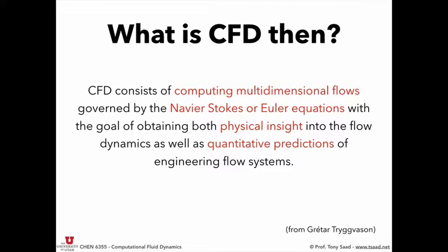We're going to focus on computing multidimensional flows. We may be stuck with 2D for all practical purposes in this class because 3D is going to be expensive for us. But computing multidimensional flows governed by the Navier-Stokes or Euler equations. Okay, and those two equations you've probably heard of. We'll discuss what they are. The Navier-Stokes equations govern the flow of incompressible fluids, incompressible flow. The Euler equations, they're the inviscid version of the gas dynamics equation. So if you're looking for compressibility, shock waves, we look at the Euler equations, or their viscous version, with the goal of obtaining physical insight and quantitative predictions into complex flow.